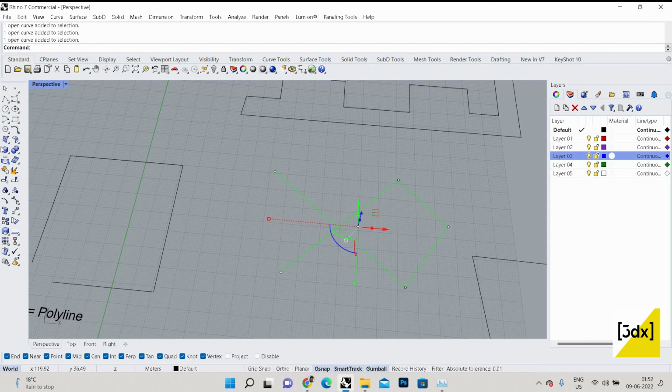So when I use Ctrl J on this one, you can see it's been joined. Now when I use explode, you might think after joining and giving explode, it will explode as 3. No, you can see these 2 have been exploded, and this one I drew as a polyline, as a joined one, but you can see this one is also exploded.